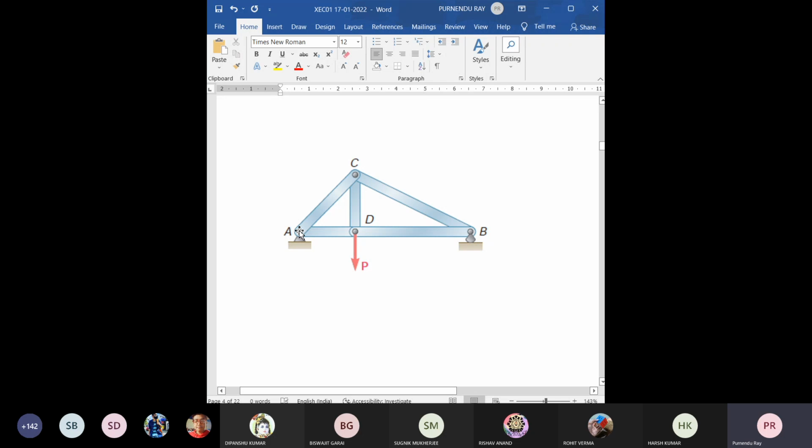But at A, you cannot slide it horizontally, you cannot move it vertically. Here also you can move it vertical upward, but not vertical downward. So vertical downward movement is restricted, and opposite to that, some vertical upward reaction will be there. So force will be such that P cannot be applied vertical upward. In that case, it will collapse, it will start rotating because it leaves this support. It is free to move upward and rotates in anti-clockwise direction, and it is not giving you that support framework.